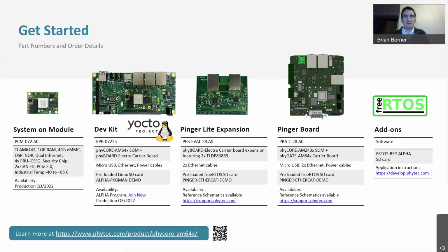But yeah, one thing worth mentioning from the questioning, I know True mentioned this, the programmable real-time unit is what True was referring to with the AM64. So the PRU is a multi-purpose interface, right? So it's the programmable real-time unit industrial communication subsystem. It's a mouthful, so we call it the PRU-ICSS, and that allows you to achieve not just a single industrial protocol, but a variety of them, and they can be programmed however you see fit.